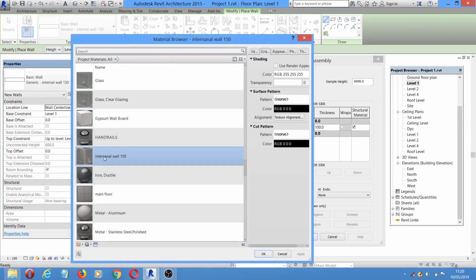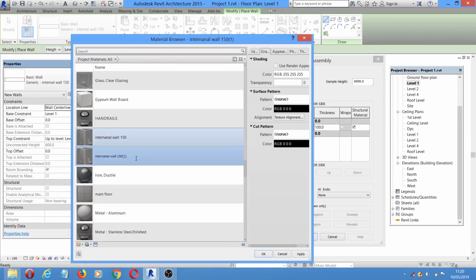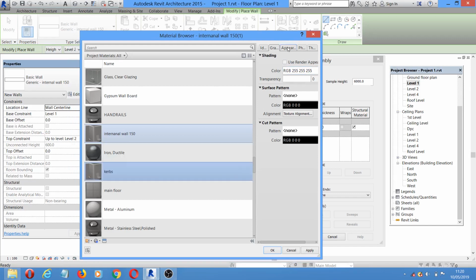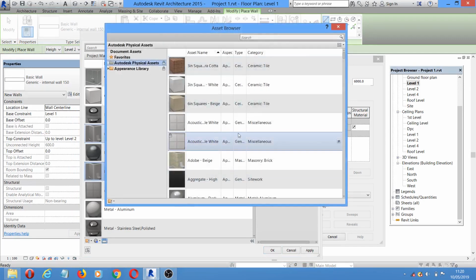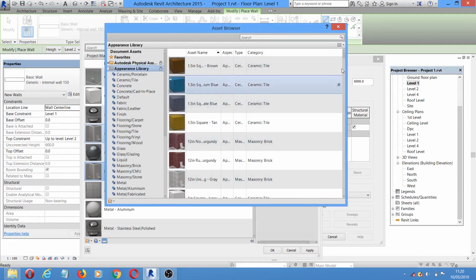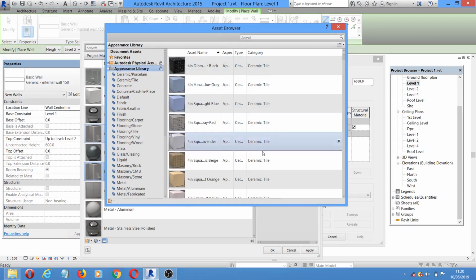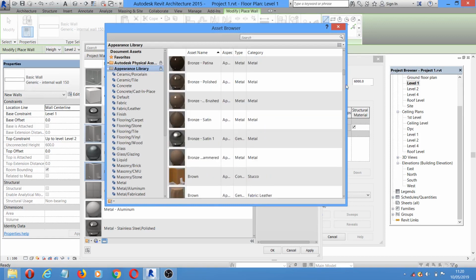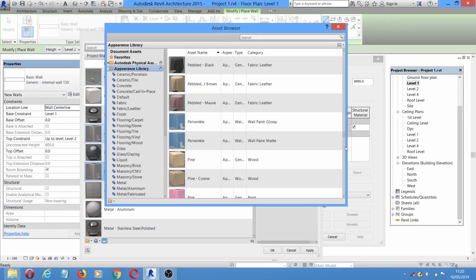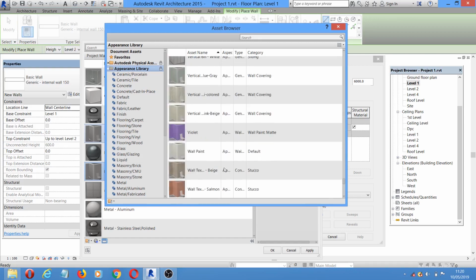Then the material we use, we can select any of this material, duplicate, and give it a name caps. Then we'll select the render appearance, click on this little button and select something that looks like caps, although we are going to modify it in 3ds Max.